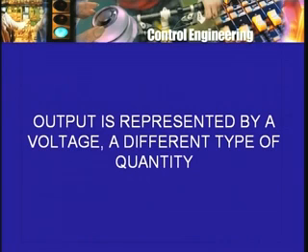Now this is one way of rectifying the situation. All that I have done is I have kept everything else the same, tacho generator unchanged, gain Ka unchanged. I have simply changed the reference voltage so that it is not 20 volts, but it is 21.15 volts. And why didn't I think of it earlier? Because the thinking was that the desired voltage should be 20 volts, because the tacho generator output voltage at the desired value is 20 volts. And so let's have reference voltage equal to 20 volts.